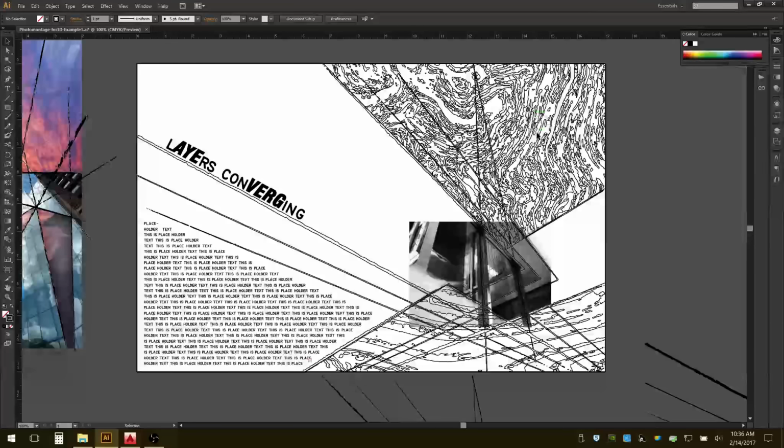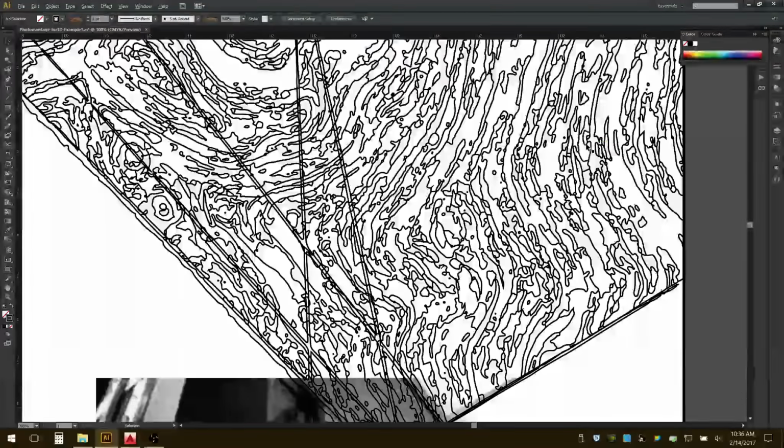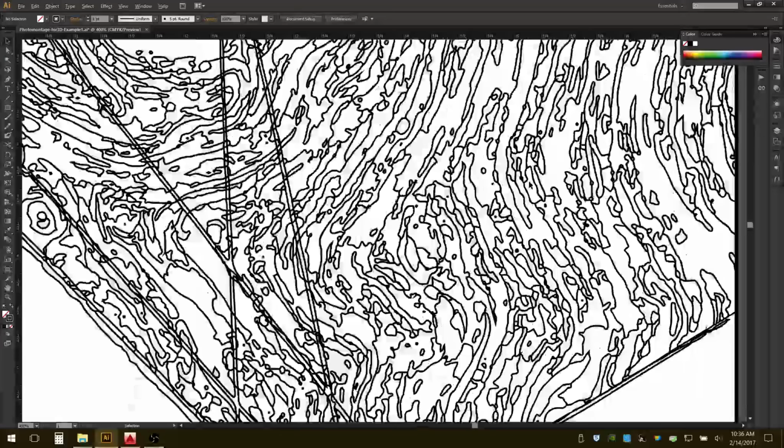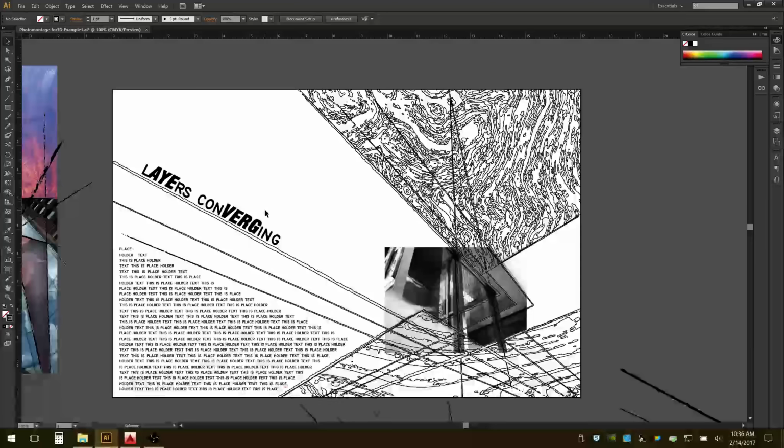So now you can see I have all this line work, and basically what that is, Alt key and the mouse wheel here. Now it's just line work. Now I can do something similar to the text, although the command is a little bit different. So right now this is editable text. If I double click on it with my selection tool, I'm able to still modify that text, but I want to turn it into just vector line work here.